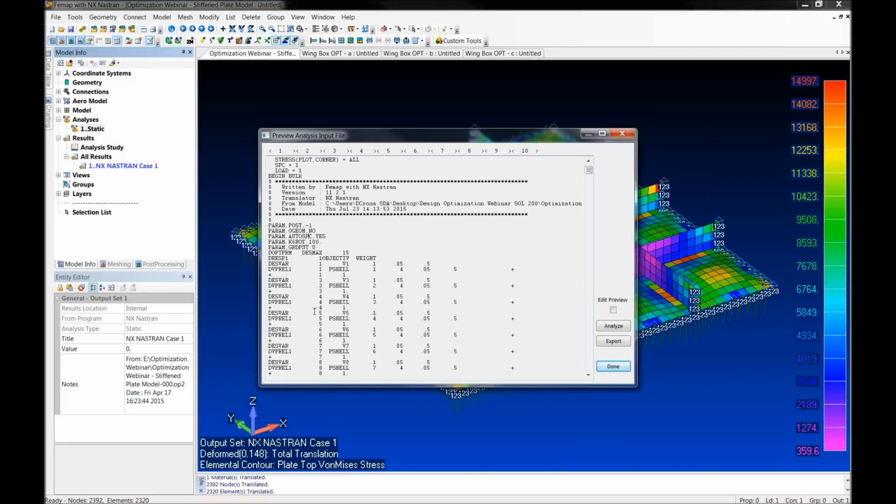And if we go down here a little bit, here this is the d-optim parameter, design variable max iterations 15, just to give you an idea. And you can see it auto-filled in our definition. So here we have our objective function. We're going to minimize weight. We have our first design variable ranging from 0.05 to 0.5.